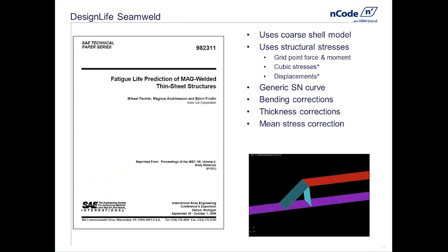Again, we're utilizing structural stresses. There are several methodologies in DesignLife for that. We're going to focus in on the grid point force and moment approach. That was the original approach from the initial paper back in 1998, and again, it is a recommended approach today.